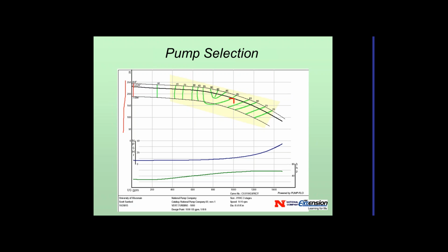So that's an example. This particular one, can you have a range of impeller sizes in it? The one that we're using is 8.5176 inches in diameter, and if we follow that around, this was designed for 1,000 gallons per minute, which across the bottom here is my gallons per minute. So my operating point is going to be right here. It's about 175 feet of head at 1,000 gallons a minute, and at that point, it's going to have an efficiency of close to 85%.